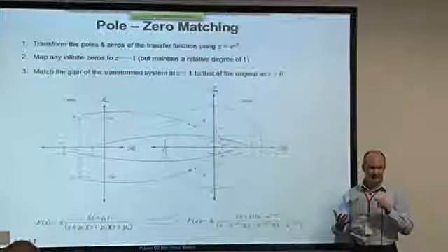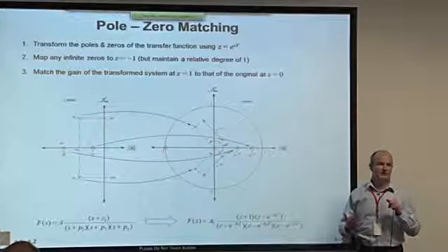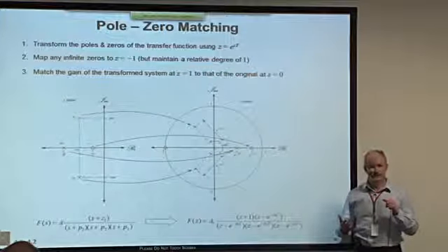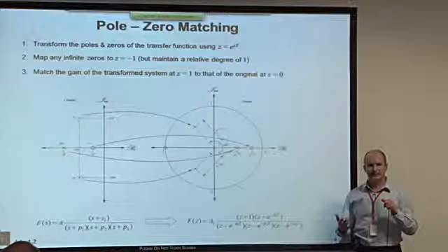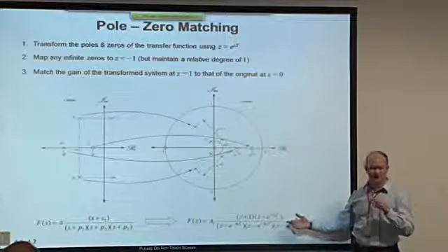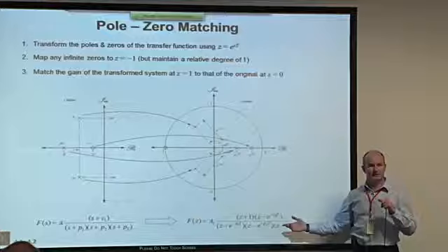When we deal with power supplies, for example, it's very likely that you'll be transforming a controller with an integrator in it. The DC gain of an integrator is what? Somebody said infinite. It's infinite, right? So how am I going to match the gains? The answer is you can't do it.